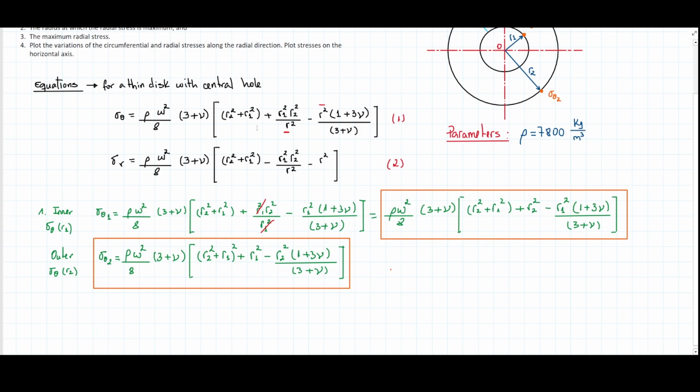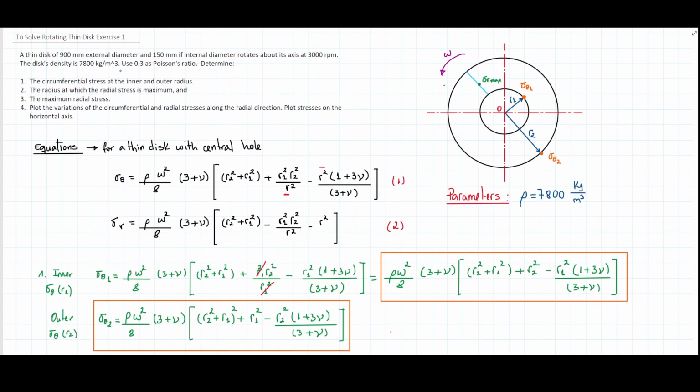So it is important to notice that the units we're using here are kind of in different scales, to put it that way. For example, if we're using density in kilograms per cubic meter, then we need to operate with the diameters or radius, and we would need to change either one of those to match the same units. So let's change diameters to meters, and then we will have everything with the same type of length unit. And then also this 3000 RPM. So let's turn it into something we could use together with these other parameter variables. So let me write this one.